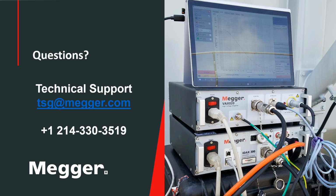If you have a higher signal, then you have higher capability of suppressing the noise because of a better signal to noise ratio. But as I said, in theory, and for the majority of cases, if you're working in a 138 or 230 kV yard, your Idax 60 Hertz power factor measurement would match the 10 kV power factor measurement.